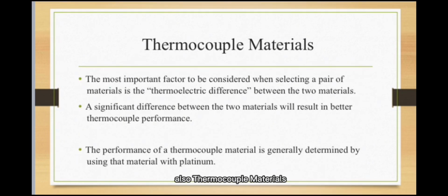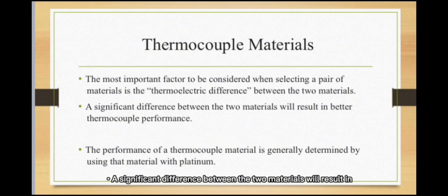Also, thermocouple materials. The most important factor to be considered when selecting a pair of materials is the thermoelectric difference between the two materials. A significant difference between the two materials will result in better thermocouple performance. The performance of a thermocouple material is generally determined by using that material with platinum.